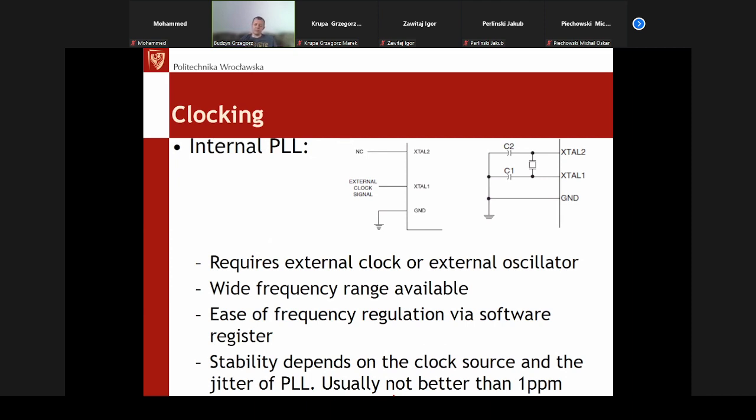Especially if we talk about a couple of hundreds of megahertz microcontroller, then generating those 200-300 megahertz on the PCB means that we will have some PCB track that will work as an antenna and will start to emit those hundreds of digital switched high frequency signals to the ether and to all the devices around.